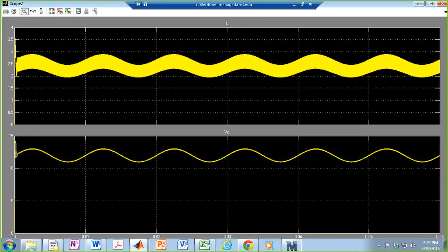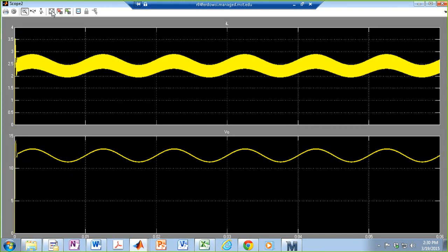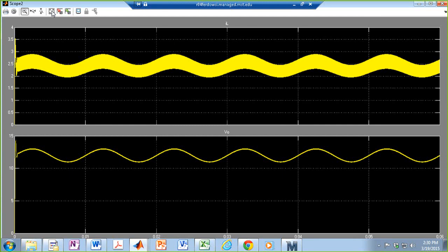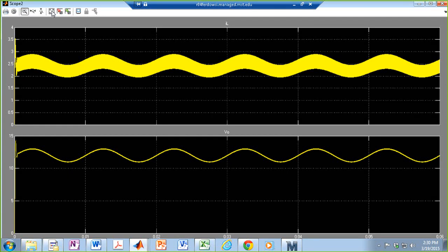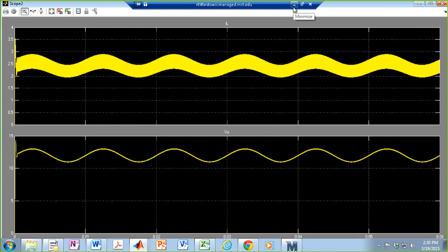in the voltage mode control case, since I'm perturbing the input voltage, those perturbations are actually appearing in the output voltage with the ratio of D, which is 25%. Whereas in the current mode control, it did not actually appear, or almost did not appear. So this is one of the advantages of current mode control. You actually have a very, very low or small audio susceptibility, which is great.